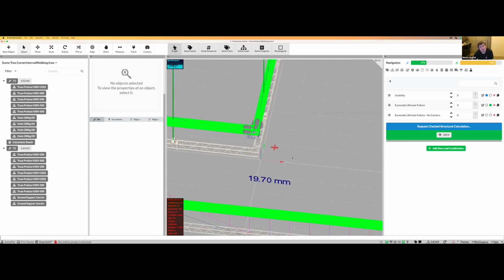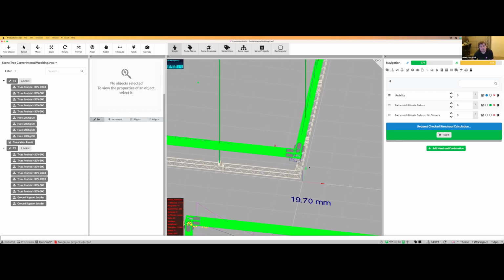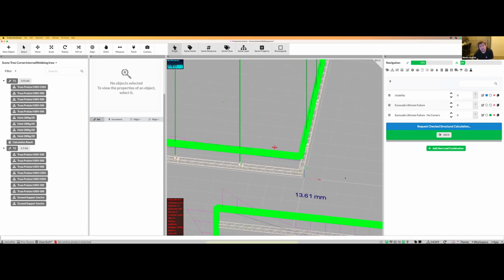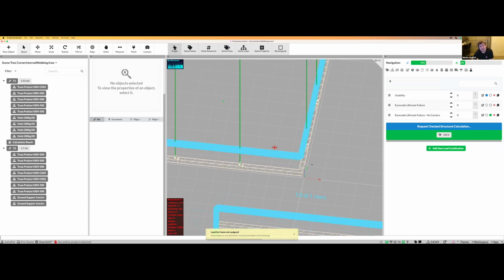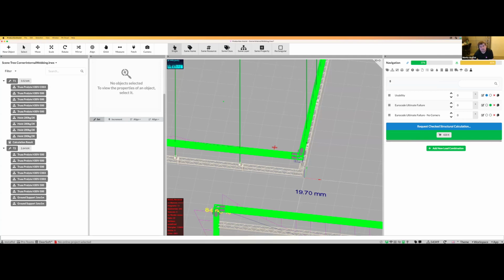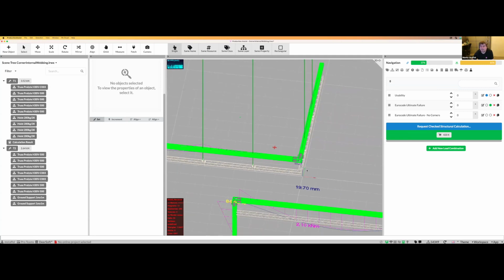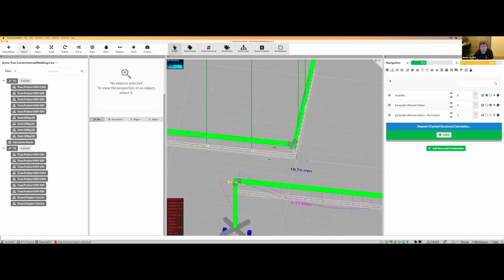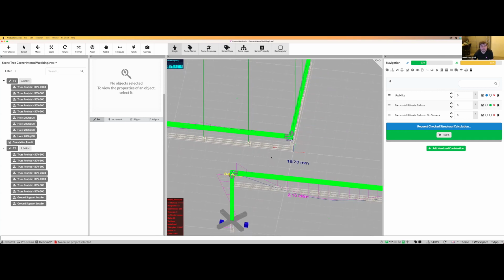An interesting thing is that it does not really matter if you do this in the normal calculation for the laying or hanging truss structures. As long as there's not much bending moment on the corners and not that much shear force, they are normally loaded fine. That's normally not a problem, but it's definitely worth checking if you have some special corners in there.